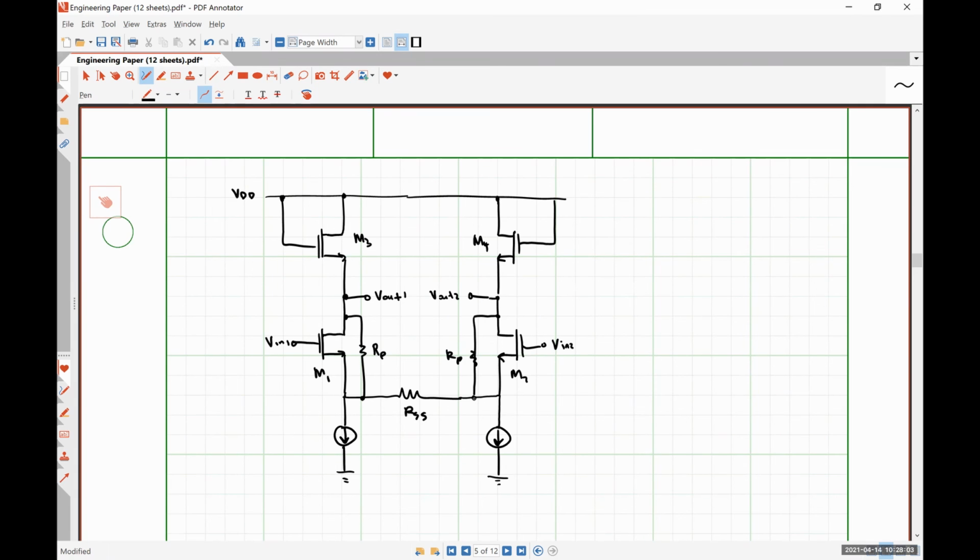So are they NMOS or are they PMOS? Let's start there. They're NMOS, and they're diode connected. So each of those looks like a resistance of what? 1/gm. Right. So we have now simplified this guy to 1/gm in parallel with r0.